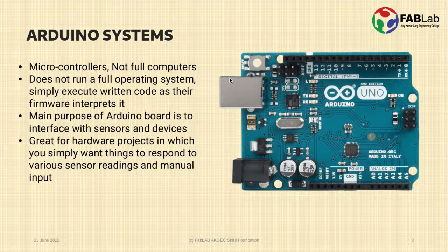Arduino is the name of the board, or you can say the name of the company which provides you the open source hardware and software platforms. It is not a computer, not a dedicated or much more powerful computer, it is a simple microcontroller. You can easily see in the center of this Arduino Uno board there is a chip that is the heart of the board, and it is a microcontroller. In the case of Arduino Uno, we are using the ATmega328P microcontroller, which is an 8-bit microcontroller from Atmel, now known as Microchip. But on this board, we can also see that some more components are included.